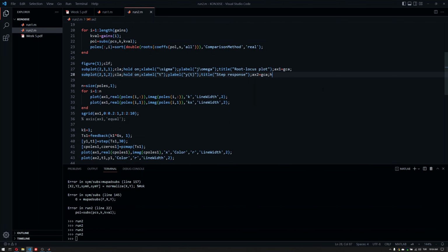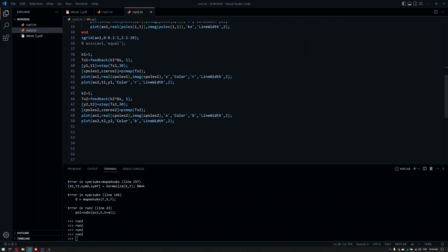Let's have hold on and then legend show, and we can give them display names here. Display name, and then maybe directly num to str k1 here.